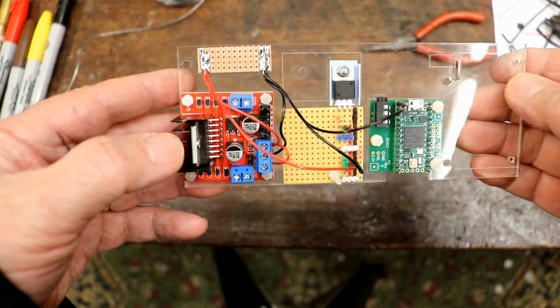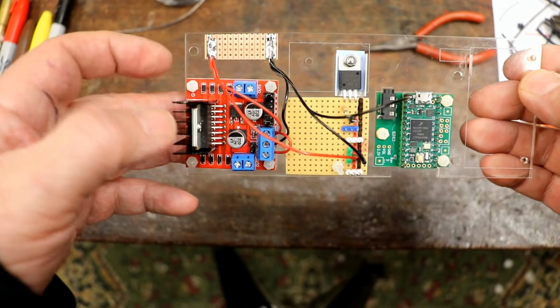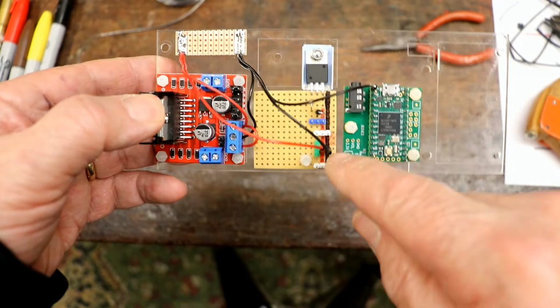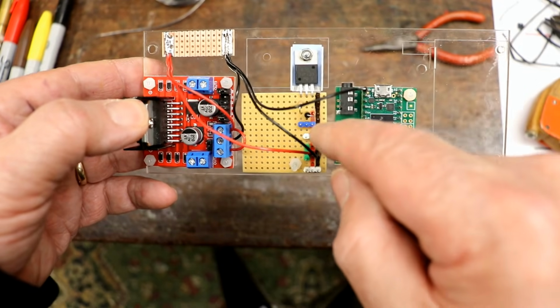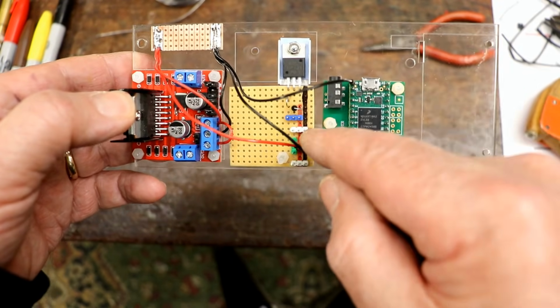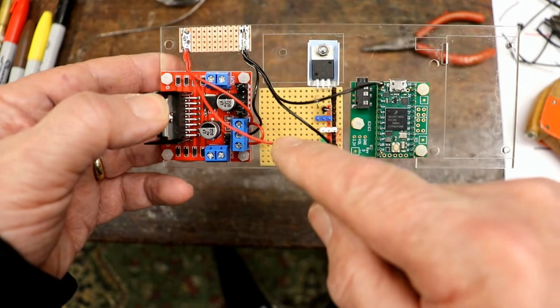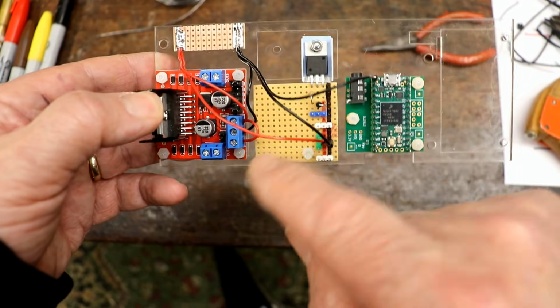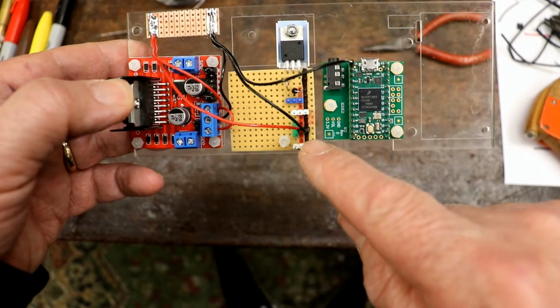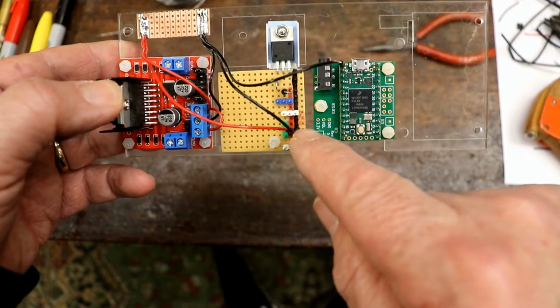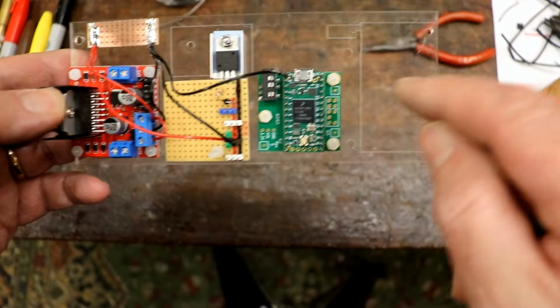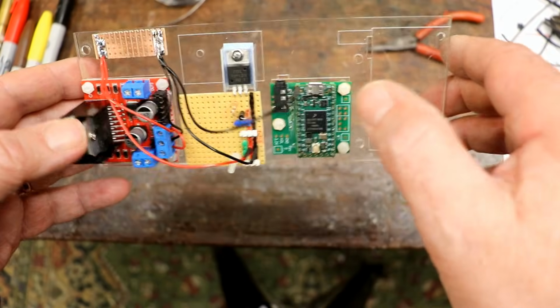So now we have plus 5 volts to the interface and to my little collection of bits here, which is going to do the solenoid and the two servo motors. So that's nice, they've all got supplies. And we've got ground going to the interface for the motor, and to my little collection of bits, and also to the Teensy. Connected that to ground.